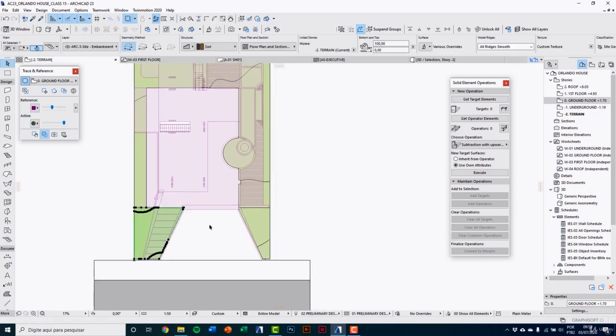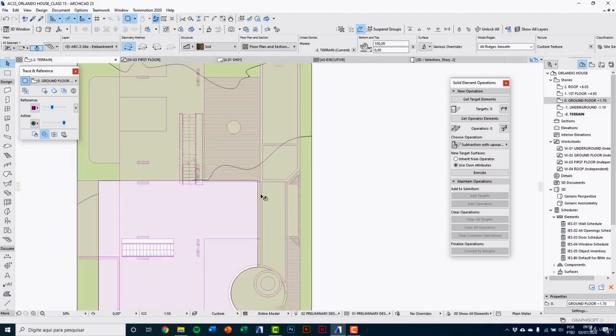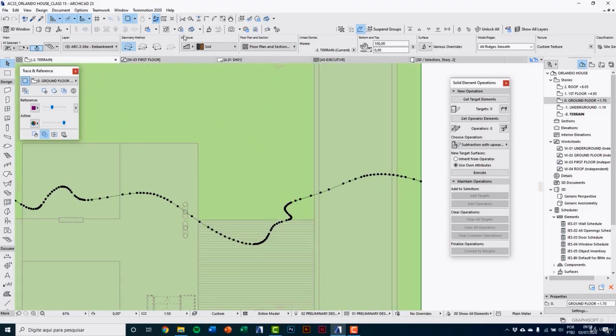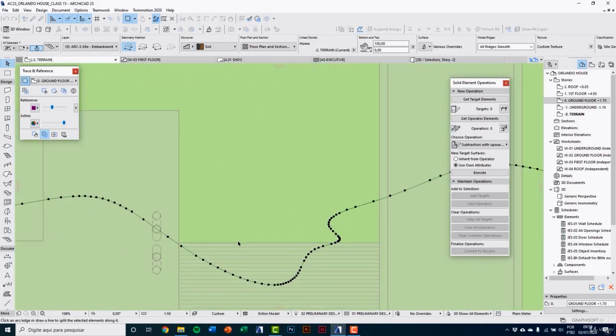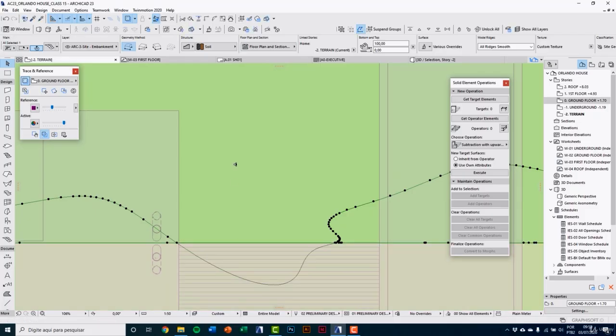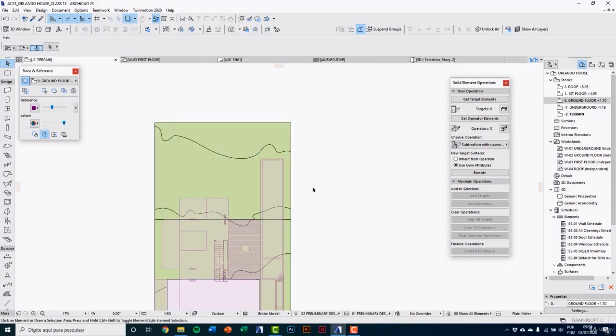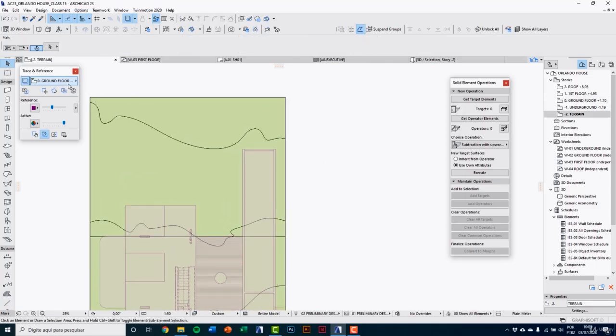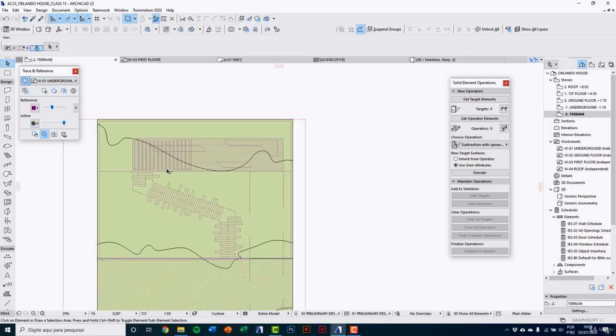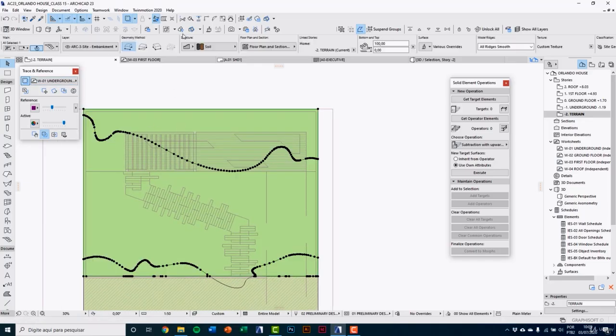And now I'm going to use the split command at the edge of this deck. Split, I do a click. The eye appears, I can select, and the division is done. Place DWG reference from underground and do the division at the limit of the deck.